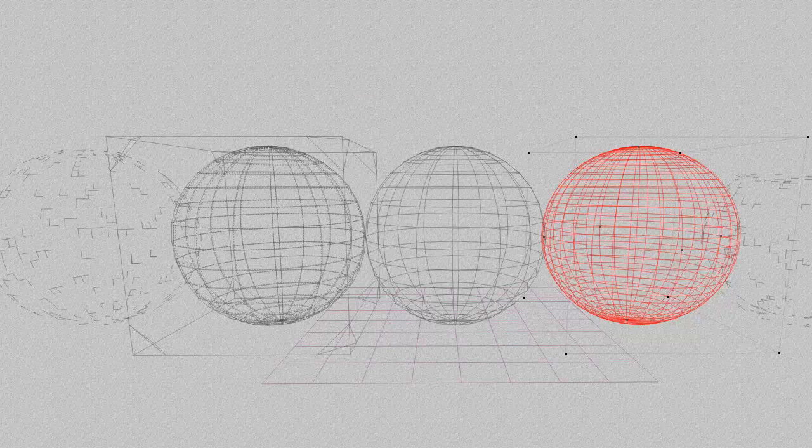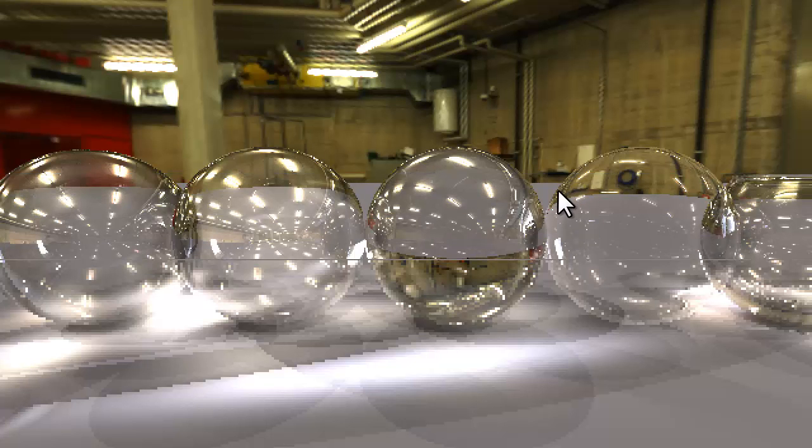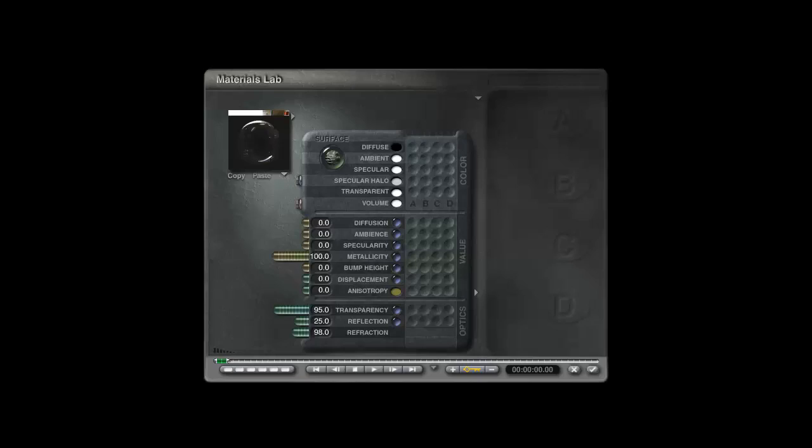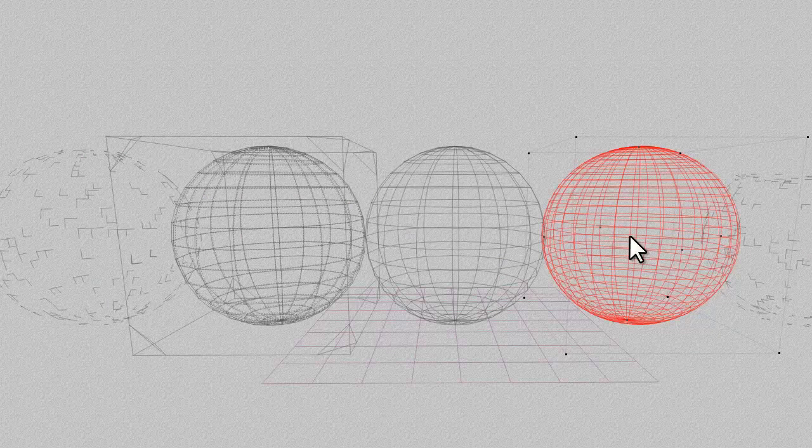So I've tried 98. Let's have a look at how that matches. It's sort of like this one. So it depends on the thickness of your glass. If your glass is very thin, then yeah, probably 99 is a good choice. I'm going to use that value there. So I've got 99, and that's looking about right there. Probably need a little bit more reflection.